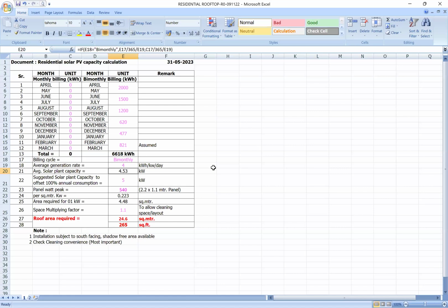So it is a huge investment, and right now it is not advisable. It is better you go by net metering. That is what our suggestion always is, because that is not an economical way of implementing things. To get the benefit of that 50,000, it will take you at least 5-6 years, and by then the battery's life will be over.